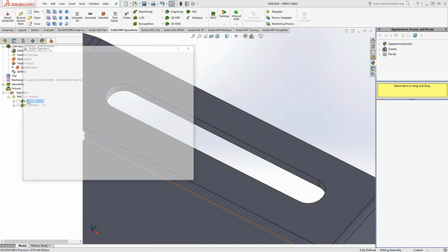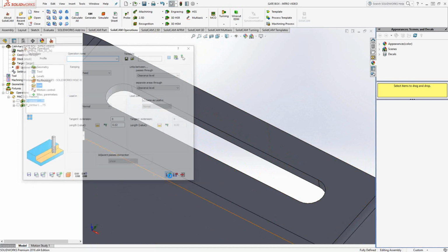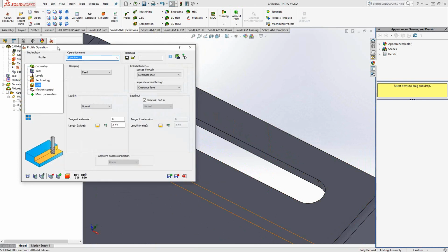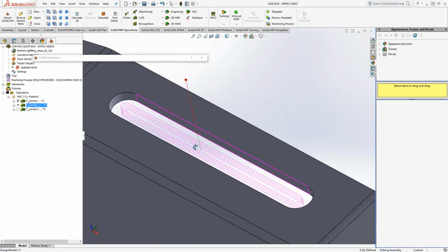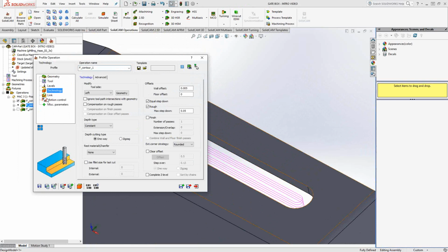Now, if I make a save and copy of this toolpath, our original toolpath, rather than doing a constant step down, meaning that it plunges in, does a lap, and then feeds back in and does another lap, we actually have what's called a helical depth type. This will allow us to apply a constant Z force, constant downward force to the tool while it goes in the Z direction and progresses down with a helical depth.